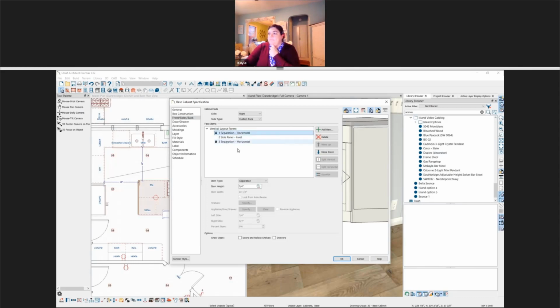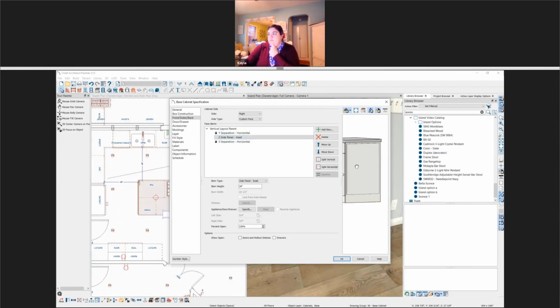which means the side of my cabinet doesn't have anything applied. It doesn't have an inset face frame. That corner automatically starts out with your 3-inch style or whatever it is. It's a solid side. Instead of having a 3/4 inch plywood end, you have a wood paneled end.